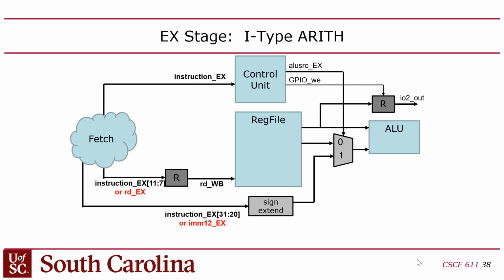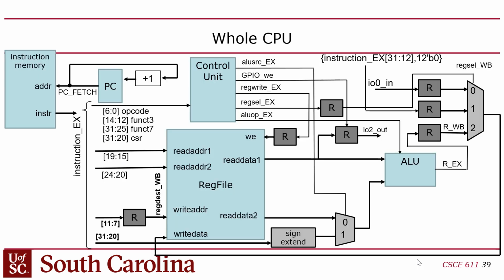Their reasoning was, there is no sign bit if you're doing logical instructions like an AND or an OR or an XOR. The sign bit is meaningless. But then RISC-V just said, just sign extend, even for logical instructions, because it simplifies the hardware, obviously.